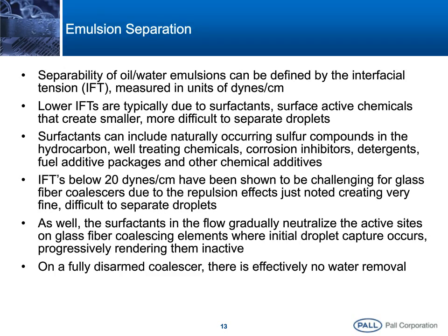So looking at some key points from emulsion separation, separation of oil-water emulsions can be defined by the interfacial tension measured in units of dynes per centimeter. And typically, as you increase the volume of surfactants present, you will see a lower dynes per centimeter number being measured. Lower IFTs are due to these surfactants. These are creating more difficult to separate droplets, as we saw, due to the surfactants, and are also contributing to